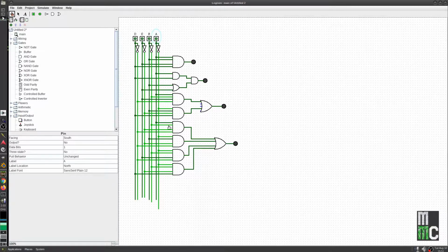Let's say you have a condition now where you want to say, well, I either want a situation where only one is on, but I also want a situation where they are all on. So here is our all on gate right here. And here is our only one on situation. What I can do, the first thing you might want to do, is you could add a circuit label, say something like this. I'm going to say only one on, and up here I'm going to say all on. This helps you keep everything straight in your head. So those 2 conditions are met.